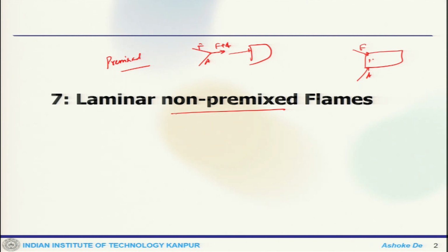So, it is clearly a difference, and it gives you some flexibility, but obviously non-premix flames are rather well known for producing a lot of emissions, like emission gases, soot and all these. They are also quite easy to handle, or rather they are stable, but you pay the price in other factors. So, again, all the time this is a process of optimization.